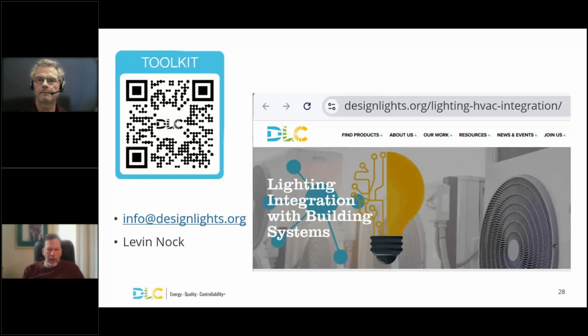That's method one. Method two would be to use a supervisory interface from the lighting system to a supervisory interface on the HVAC system. Those two supervisory systems would talk with each other, either using BACnet, or a standard API, or a direct Ethernet connection with a data protocol on top of that, like MQTT or REST.